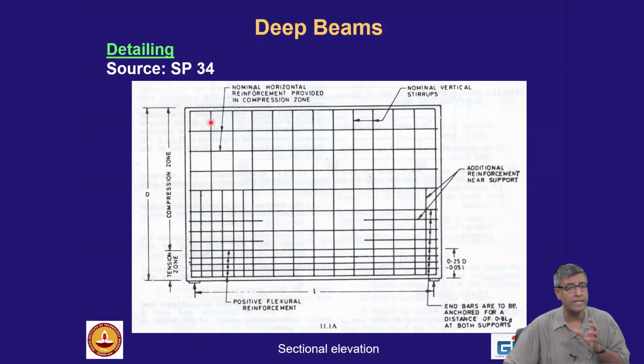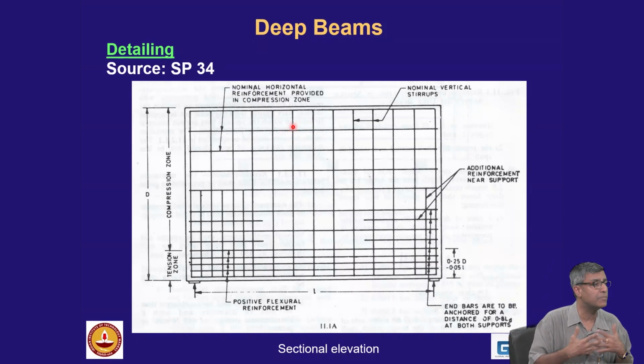This is not as per the conventional shear design. This is because we do not need shear reinforcement theoretically. In your strut and tie model, the load is directly coming to the supports. But does it mean that I can totally get rid of shear reinforcement? No. I need reinforcement for the integrity of the struts. However, you can reduce the amount of reinforcement, say if you are using fiber reinforced concrete.